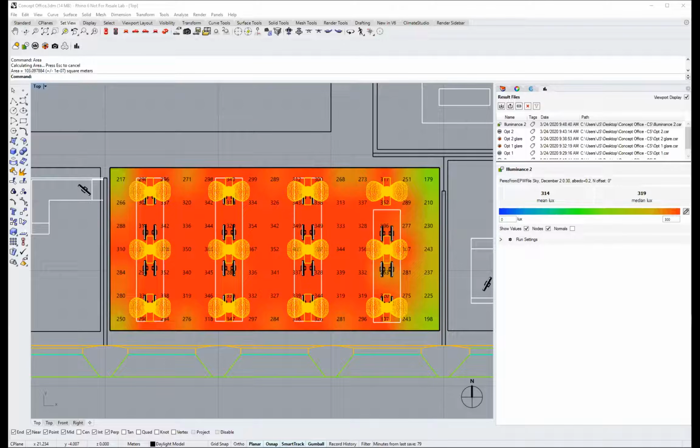There was a couple of times a question regarding why the simulation results are so fast. John spoke a little about this. I would say in a nutshell, what you should know is these results are based on Radiance. And if you wait long enough, they will be converging to the exact same numbers as you would get out of Radiance directly, with the difference, of course, being that Radiance is a stochastic program. So in both cases, you would have to run the numbers a number of times, and then you should see overlapping distribution curves.